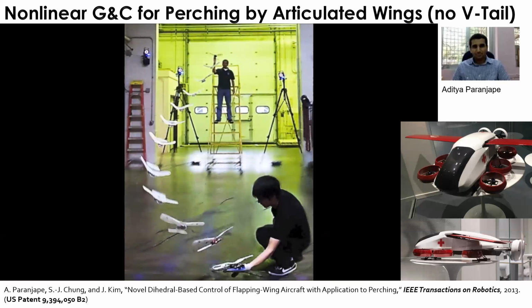So let's talk about some learning-based flight control methods. This is called the Neural Lander. The key idea is that we want to learn some unknown dynamics model. We are taking an example of landing a drone, because when you land a drone, there is a ground effect, an additional force because of the reflected airflow from these multiple rotors. The closer your aircraft is to the ground, the stronger the external disturbance generated as a ground effect.